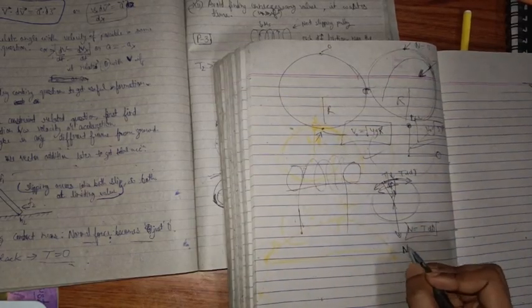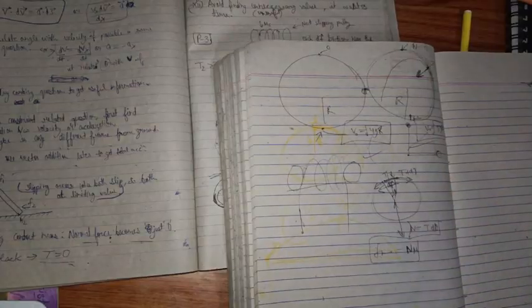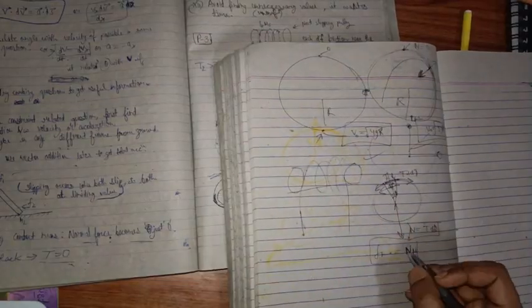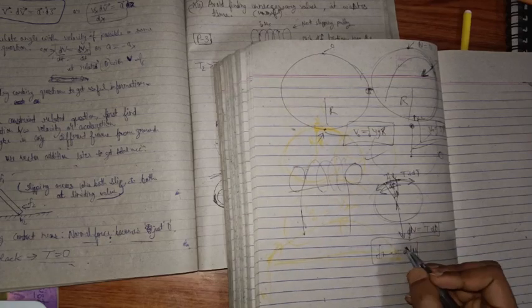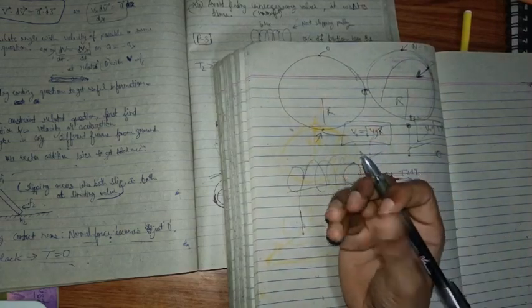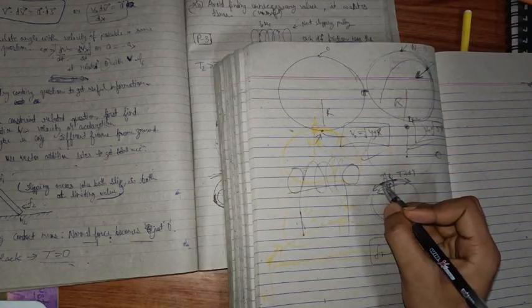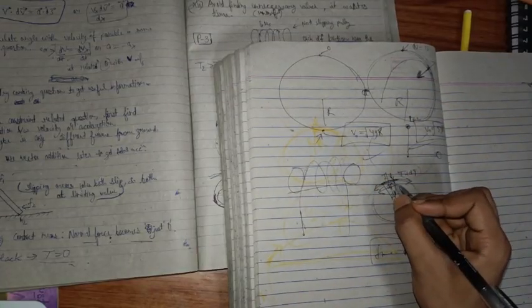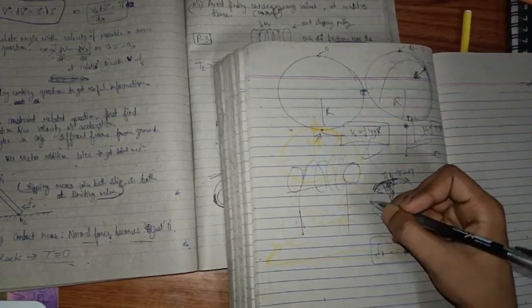This normal force into the mu gives us the f max. And because these are very small length elements, they are providing very small amounts of friction. This is dN, actually, which is a very small force, and each of these elements is providing a very small force. So if I pull it with some force, let's say tension T from this side, T plus dT from the other side, because I am providing a finite amount of tension, the tension cannot be completely cancelled by this small amount of friction. So this friction will reach its peak value, then the element behind it, the length behind it,